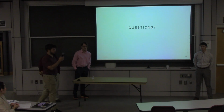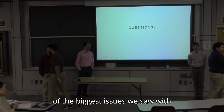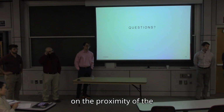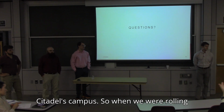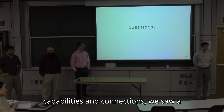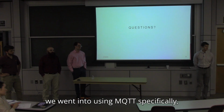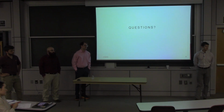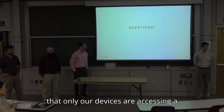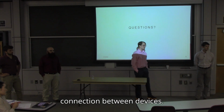One of the biggest issues we saw with Bluetooth was there's a lot of devices in the proximity of The Citadel's campus. So when we were rolling through and we were testing for Bluetooth capabilities and connections, we saw a lot of MAC addresses popping up. And when we went into using MQTT specifically, we could set a username and password so that only our devices are accessing a specific network in order to provide our connection between devices.